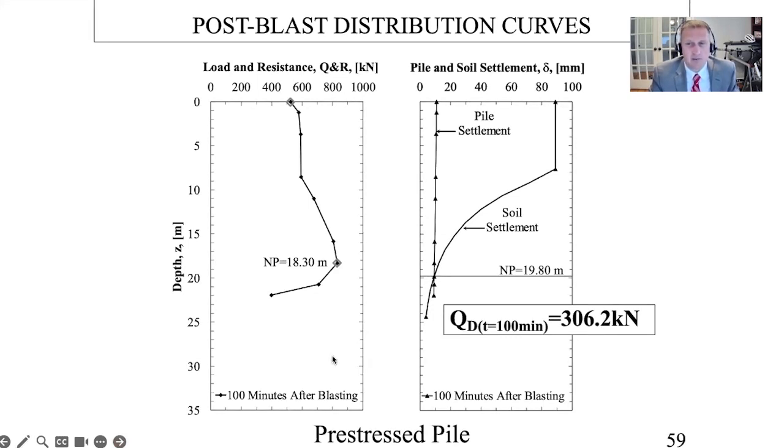And note, different piles had different amounts of drag load that developed, caused by one pile being deeper and having more positive friction below the liquefiable zone than the other ones. And so that's why we have a difference, and also a difference in cross-sectional area, causing a different amount of load to be developed.